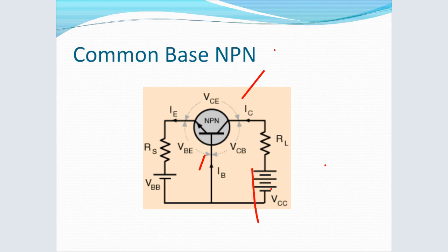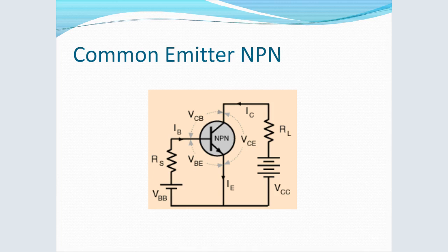Those are specific voltages that are in between those three terminals. Okay, so we're going to use them to compute mathematically how much voltage we need through C or through B to allow this particular transistor to function properly.